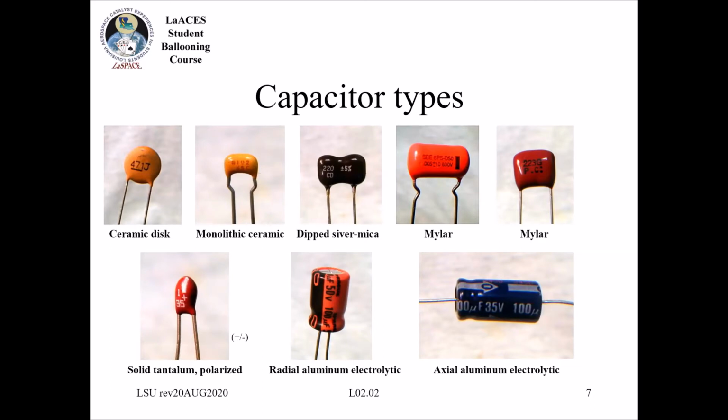I'm not going to go through all the details, but very common are the ceramic capacitors. Those are also often used for filtering, and they're probably the most standard type. And then at the bottom, I want to point out that the tantalum and the electrolytics are polarized. And you can see there's a little plus sign here. If you actually look at these electrolytics, you'll see a minus or a plus. And if you look at it and it's confusing to you, then go look at the data sheet and make sure you understand what the proper orientation is. Don't just make an assumption here about these guys.